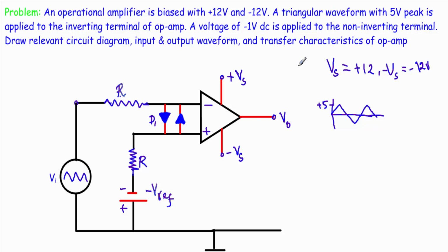At first you have to know that when an operational amplifier acts as a comparator circuit, it will contain two voltages. One is the input voltage Vi and another is a reference voltage Vref. When this reference voltage is equal to 0, the operational amplifier acts as a zero crossing detector. The output voltage will have a transition from either positive to negative or negative to positive saturation level when the input voltage crosses the zero axis.